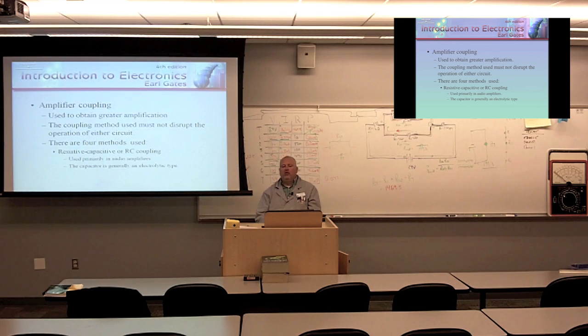RC coupling, or resistive capacitive coupling, very popular, used primarily in audio amplifiers. And typically the capacitor is going to be electrolytic. And you need to be careful with electrolytic capacitors because if you put it in a circuit backwards, it will explode, right?